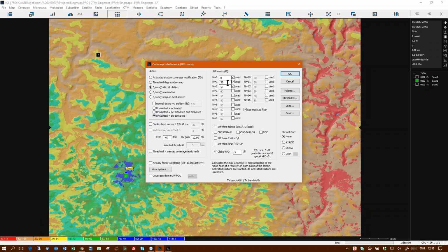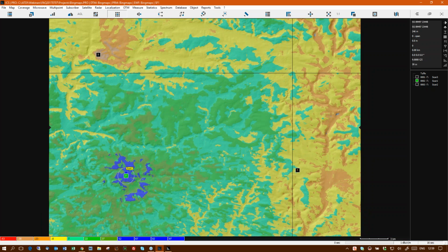So now what we're looking at is these two sites here that are slightly offset on frequency. They're deactivated because we don't want them in this plot. Fingers crossed as I flick this button. Right, what that's telling us is that if you get around this particular site here, you're getting quite a significant degradation in this one is adjacent channel. So you're getting quite a significant degradation. It's down here, -23, -38 dB degradation on what you would expect from the coverage of this base station around here, because there's an adjacent channel base station. Over here, this is a next adjacent channel base station.